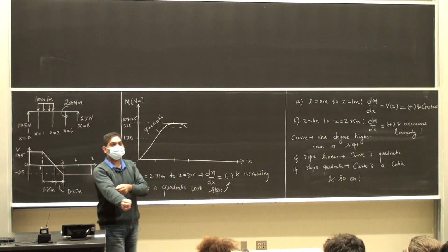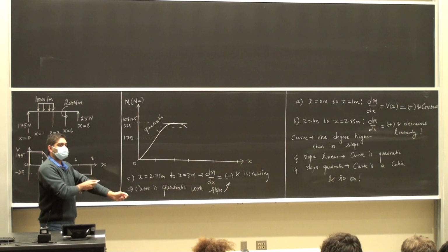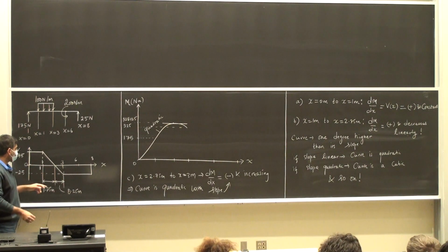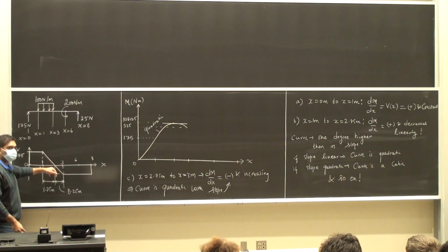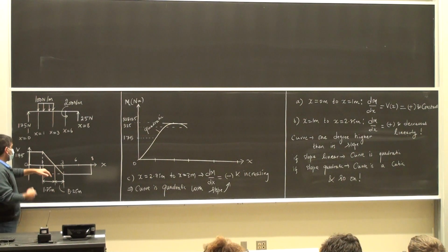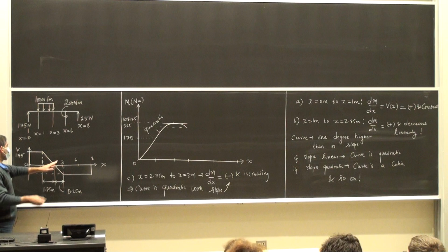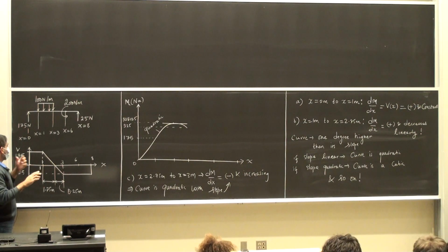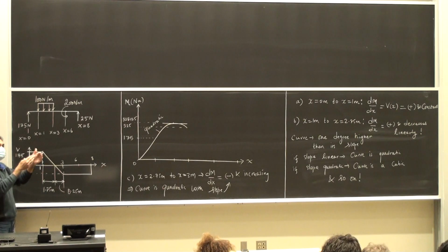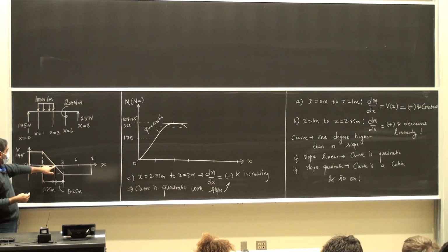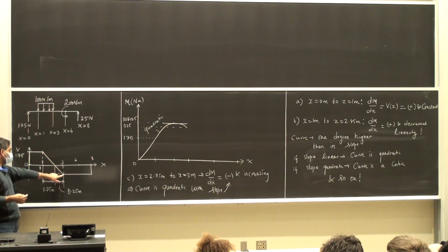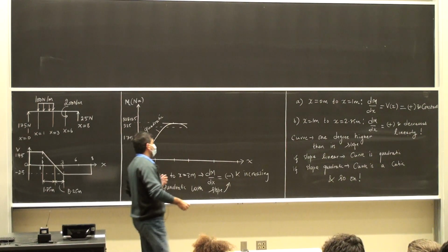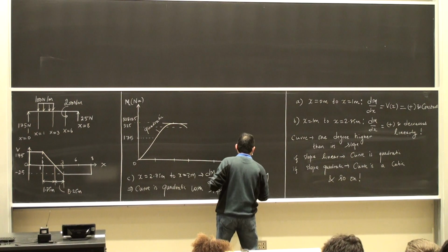Questions? Yes? On this shear force diagram, for 3, I know it's negative because it's below the x-axis, so why is it increasing? Right. So when I say it is increasing, we have discovered that it's negative, so set that aside. It is increasing because I am looking at the magnitude of the shear force, which was 0 here, and then becomes 25 newtons. Just the magnitude.